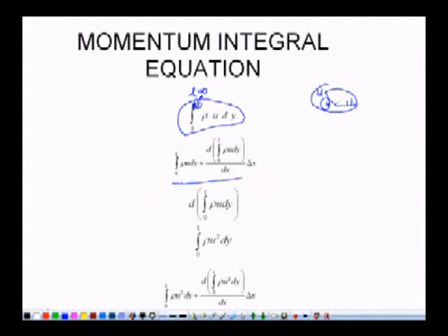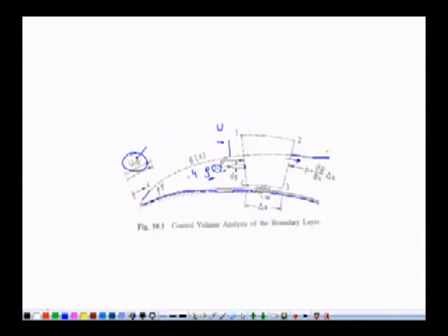So with the help of Taylor's series, we can write the mass flow rate going outside the control volume through that right face. This is the mass flow rate going outside the control volume, this is the mass flow rate going inside the control volume through face 1, 4. It is going in, through face 2, 3 it is going out, because we have a velocity in x direction.